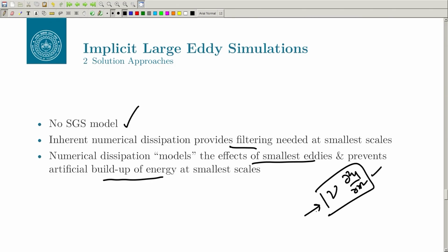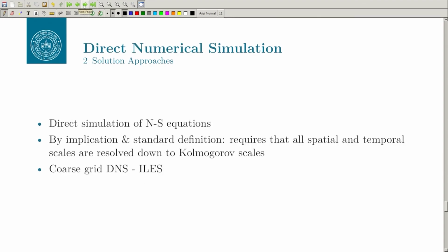So, the argument in implicit LES is that because you have the numerical viscosity, nu plus nu_n, even if your delta x is not small enough, in LES, for a sufficiently large delta x also you can get the same effect. So, that is the argument, that your numerical dissipation accounts for the dissipation that is not happening by natural viscosity, right. This is what is called implicit LES.